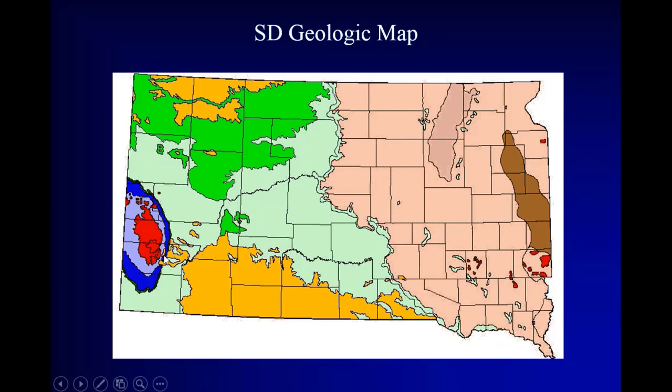But in South Dakota, you do have the quarry sources. This is the Black Hills. And these red formations, that's the Madison limestone, which is a fairly high quality limestone, which is quarried out in the Black Hills and Rapid City, Hot Springs, Spearfish, even the northern end of the hills. And then when you get to the eastern part, in this glaciated area, you have these quartzite outcroppings, which are denoted in red here.